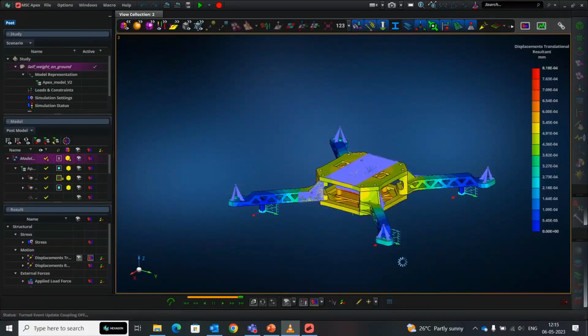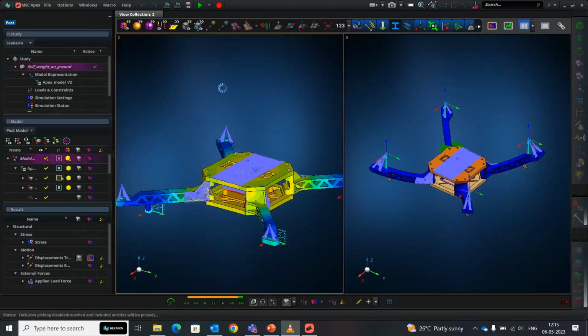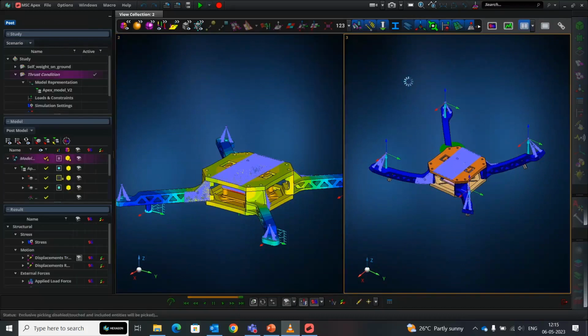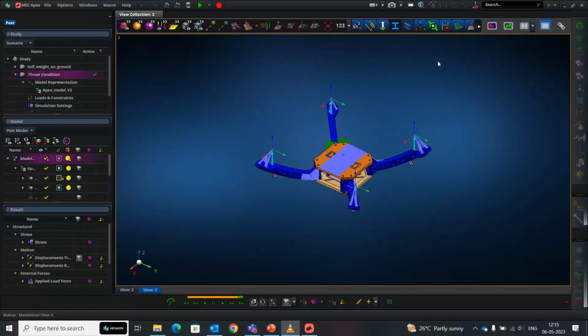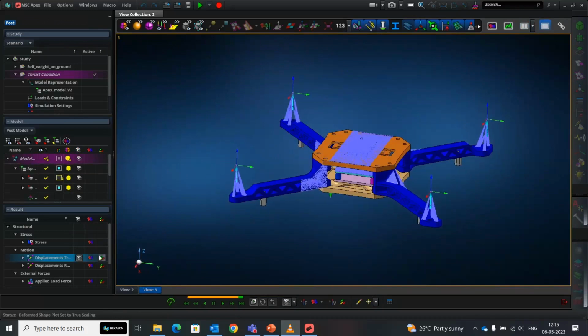And in the results, during the post-processing, you will be able to see the previous analysis as well as the new analysis. I'm just going to turn off this previous analysis. So I'm going to keep this latest analysis which we performed. Once again, the scaling will always be scaled. So you can see true scale when it's toggled. This is the actual deformation that you're looking at.